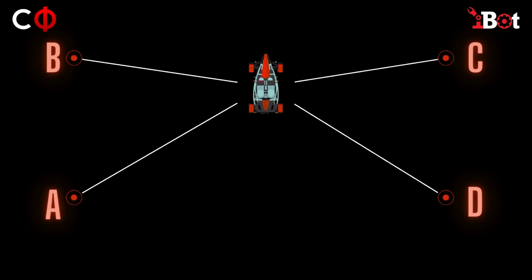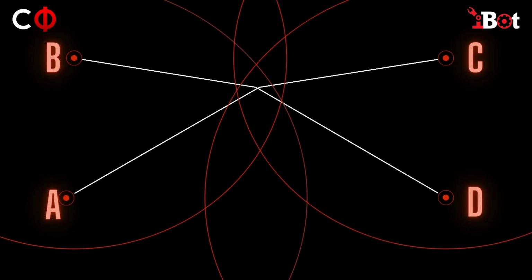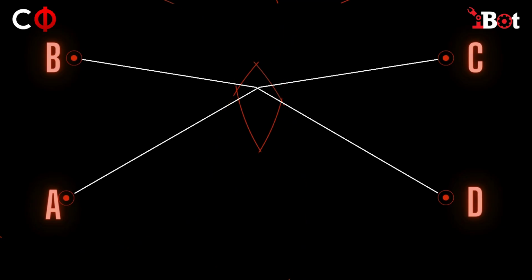Now let's take a few circles around these points and put the robot aside. According to the robot, it doesn't know exactly where it is. So let's look at how a robot can calculate this. Let's take a circle centered on each of these points, with radius being its distance from the robot to the point plus error plus a buffer we are adding, so that there will be an intersection of all these 4 circles. Now let's take the intersection of all four circles. You can see this is the area of probability where the robot can lie.